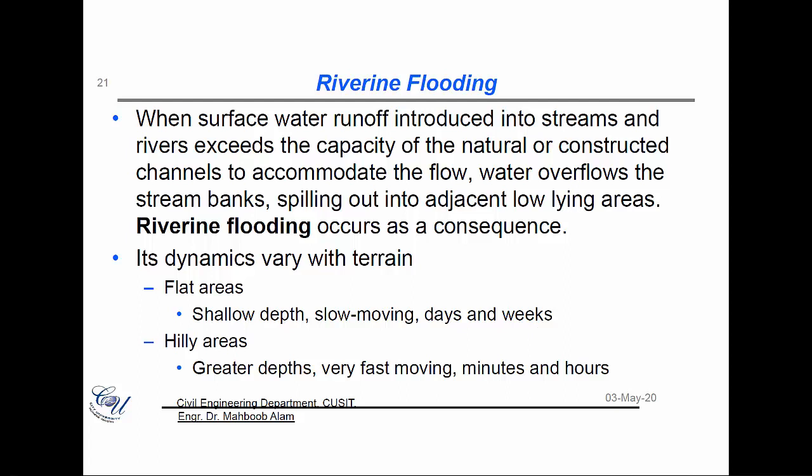And its dynamics are also very different depending upon what kind of terrain we are looking at. If the area is flat, then the riverine flooding usually has a very shallow depth, and the velocity is also slow. It has low velocities and smaller depths, and it stays in the area for a longer period of time. It can be days or weeks, depending upon how large the flood is, because the area is flat,